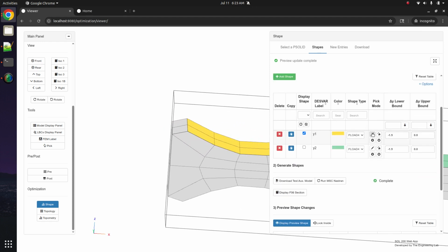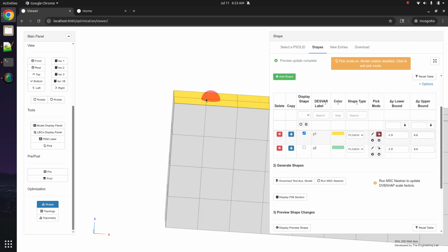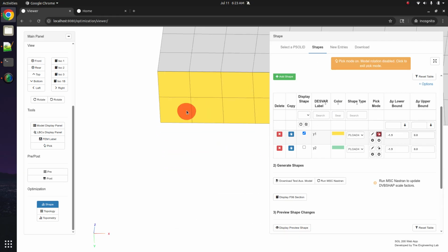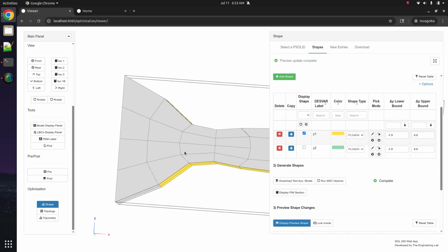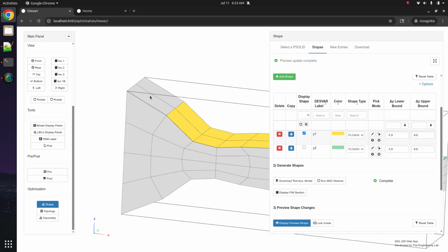Now, what I should have done a moment ago, maybe let me remove those faces from the shape. And let's look at the, right. So here, when you look at the original shapes, you can see that at these nodes at the far left side, you cannot add or remove material. Those nodes are fixed during the optimization.